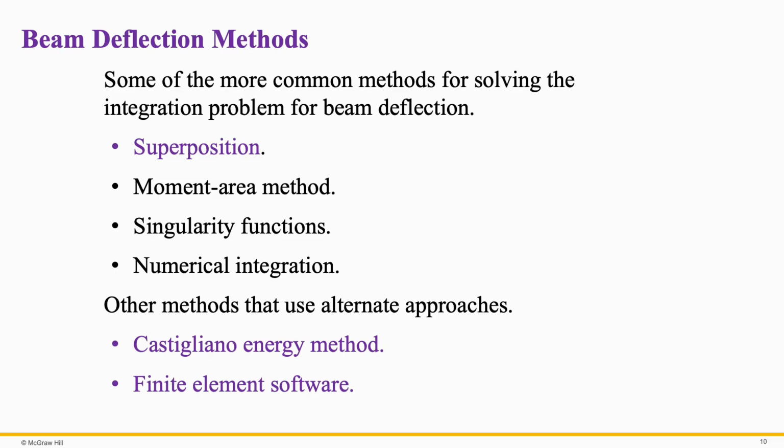Finite element software can also be used to determine deflections, and you will have a bonus assignment in which you will use finite element software such as ANSYS to calculate the deflection of this beam. But in the exam, your main focus will be on the superposition method and Castigliano's energy method. These are the two basic and fundamental methods which are frequently used to determine the deflections of beams.